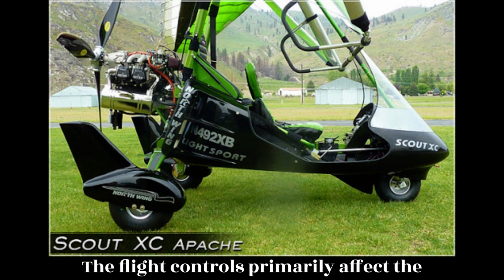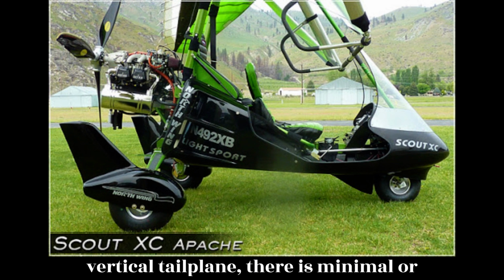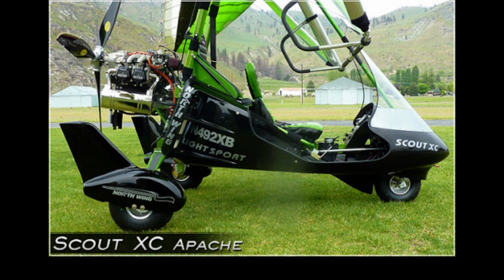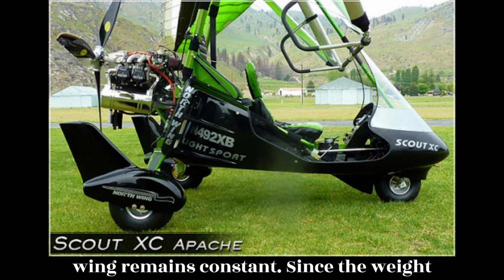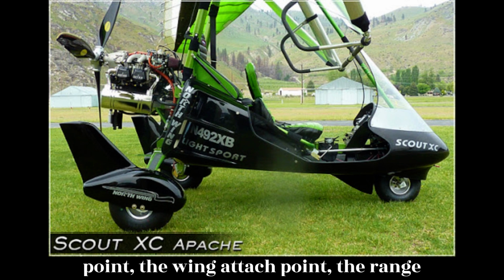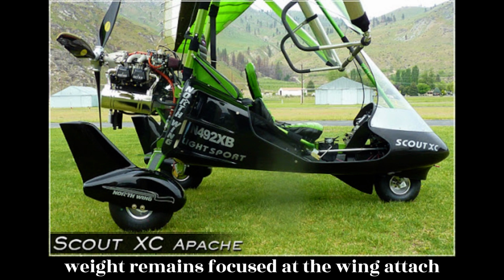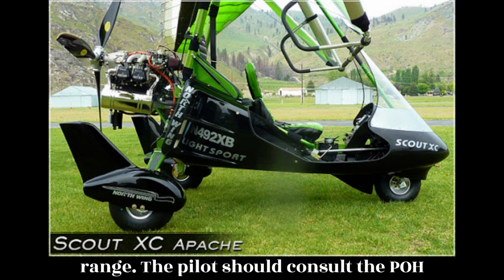The flight controls primarily affect the pitch and roll axes. Since there is no vertical tailplane, there is minimal or no yaw control. Unlike in an airplane, the CG experienced by the WSC aircraft wing remains constant. Since the weight of the airframe acts through a single point, the wing attach point, the range over which the weight may act is fixed at the pendulum arm length. Even though weight decreases as fuel is consumed, weight remains focused at the wing attach point. Because the range is fixed, there is no need to establish a calculated range.